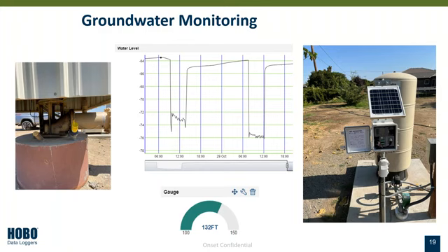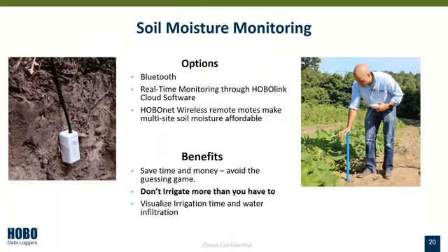Do I need to do any type of changes? And also for those of you who are big ag guys and you have some big pumps out there, you can see actually drawdown by people that are close to you. If somebody else, a neighbor down the way that's only 500 yards away, turns on his big turbine pump, is your pump affected? Is your aquifer affected? So groundwater monitoring, we're able to do that. You can see our dashboard here and a quick gauge in some of our installations.